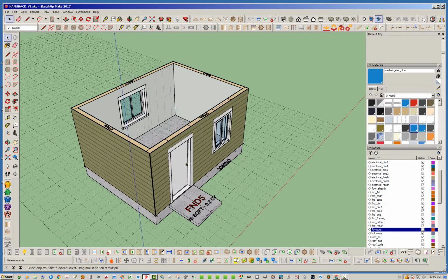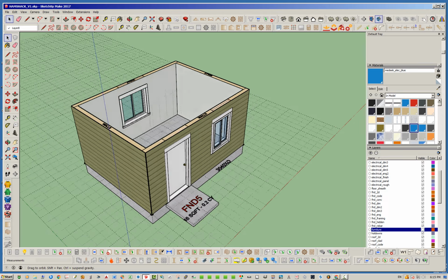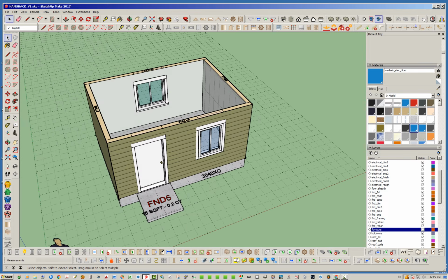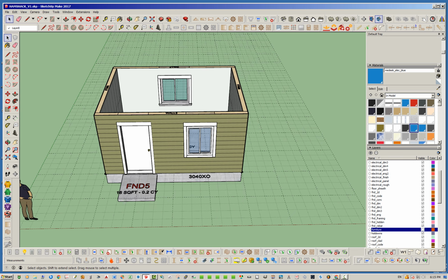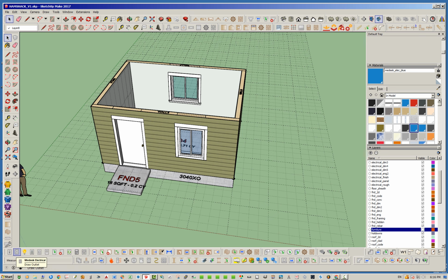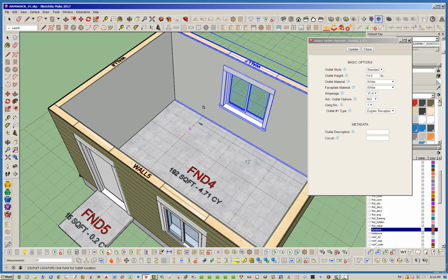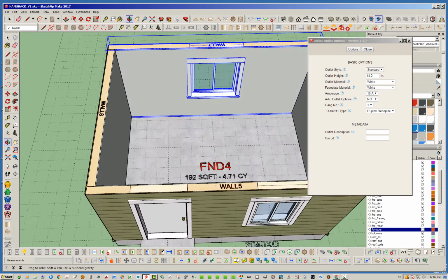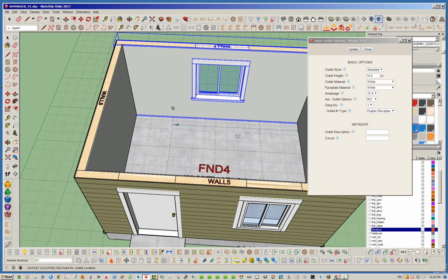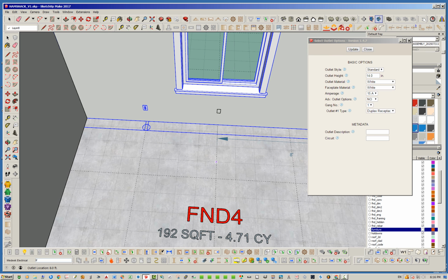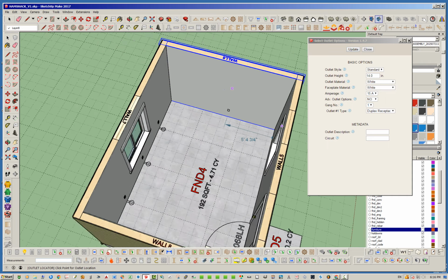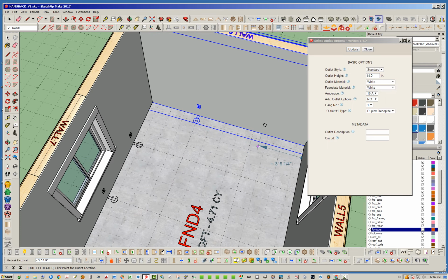I could put a roof on this guy already, but before I do that, I'm going to use the electrical plugin, which is part of the Medeek extensions. It's not part of the mdkBIM package normally, but it is one of the extensions. The reason is that I want to flesh out what I'm going to do with the outlets. With the ham shack being what it is, I'm going to get serious with outlets here, a little excessive perhaps. So I'm going to throw one in right there. I'm going to do one every 4 feet, which is well above code. I think code is like every 12 feet. But I'm going a little crazy because I'm going to be running equipment in this room, right?